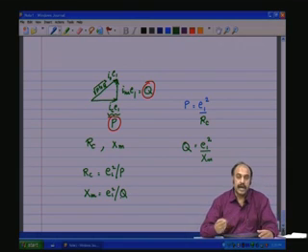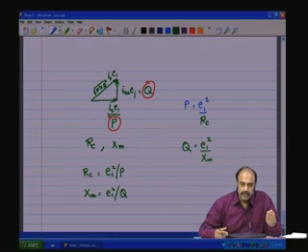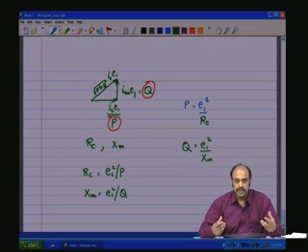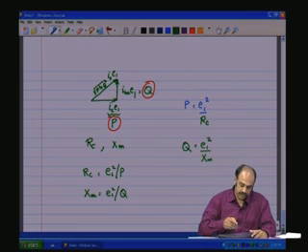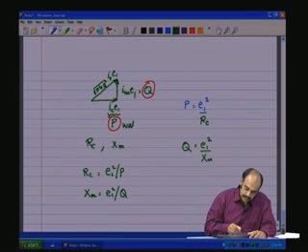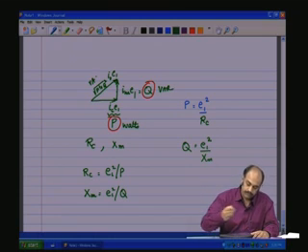So, measuring the active and the reactive power, that is measuring I naught and Eg voltage, capturing it on an oscilloscope, and then computing the P and the Q, that is the active power component which is watts, the reactive power component which is VAR, and this of course is VA.